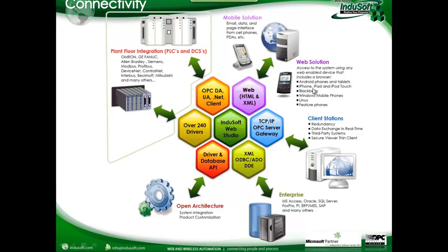It could be Android phones or tablets, iPhones, iPads, Blackberries, you name it. And we can get into variations of that via text-based, or what we call tabular, or graphical-based, that'll run on HTML5 enabled devices. We can also use InduSoft as an OPC server, or communicate to devices via TCP/IP and various variations of that. And then we can also use XML as well as different database connectivities to connect to different databases.